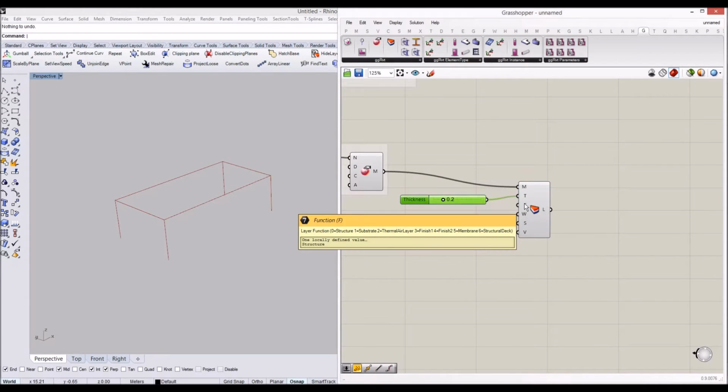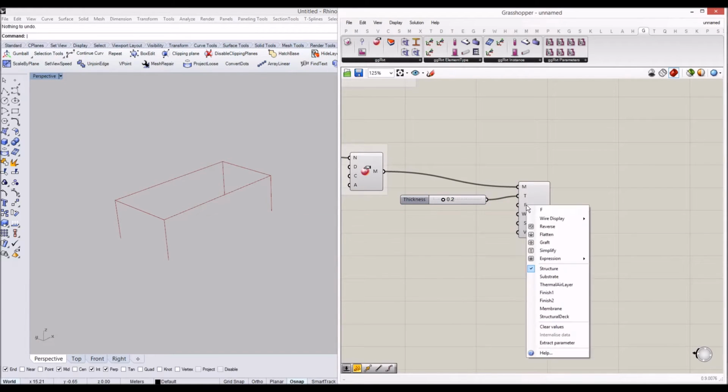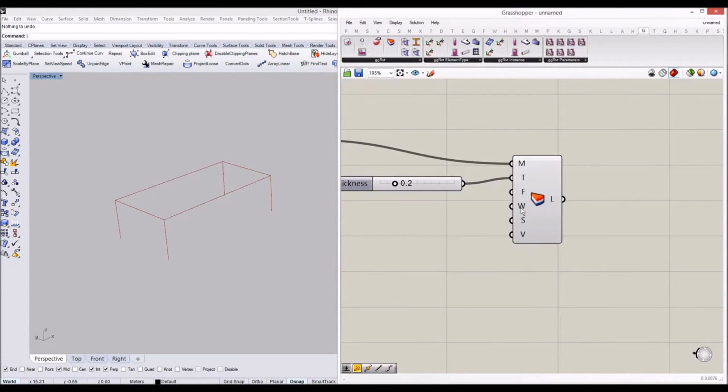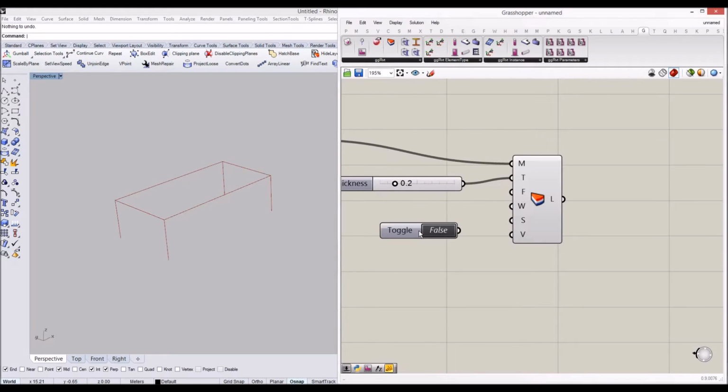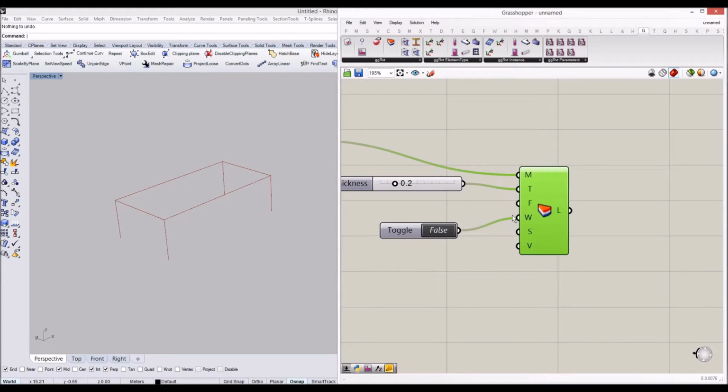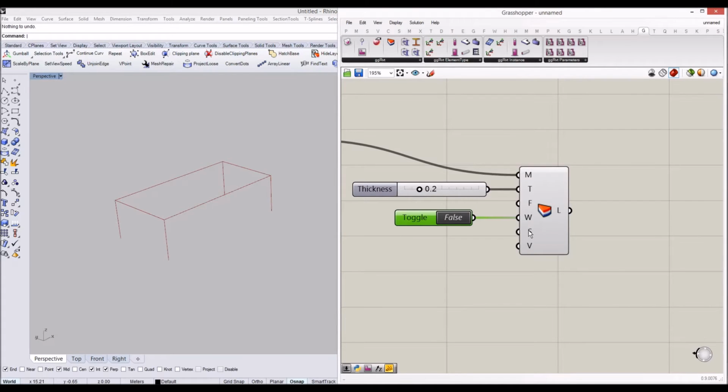And we have the function, which is structural floor, which is correct, so I'll leave the function as structural floor. And for the wrap, I'll make it not true, so let's type a Boolean Toggle. I'll make it false, because it's the core structure of the floor, it's not going to wrap our finishes or etc. And it's a structural component, which is true, so I'll leave it true.